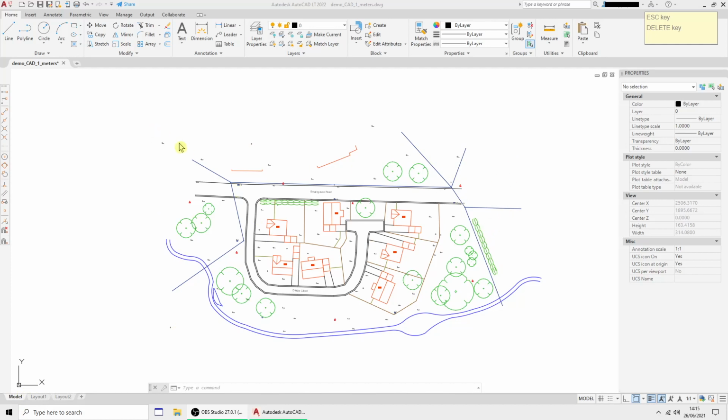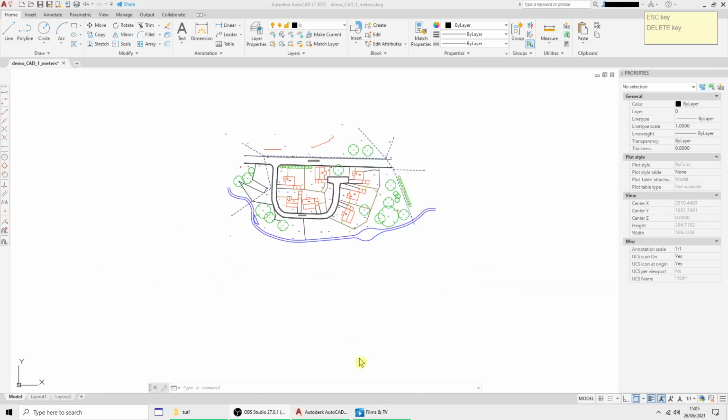It may have north sticking over here somewhere, but generally 95% of the time a topographic survey will come to you north-south and east-west along the horizontal. So we can actually use the Ordnance Survey grid, because that also uses the same axes. They can actually set the topo coordinates to the Ordnance Survey coordinates, and that can be very handy for overlaying GIS stuff from DEFRA and OS.